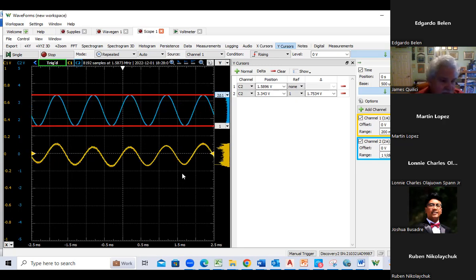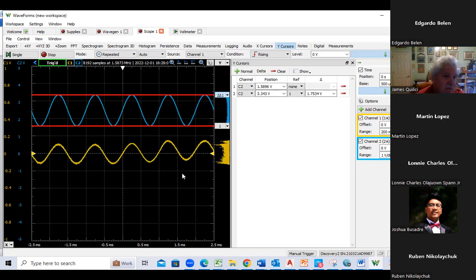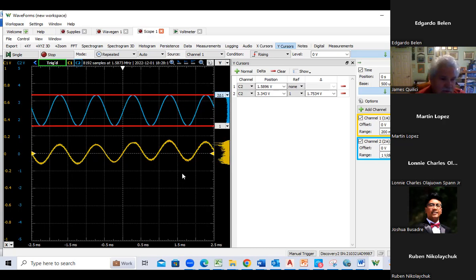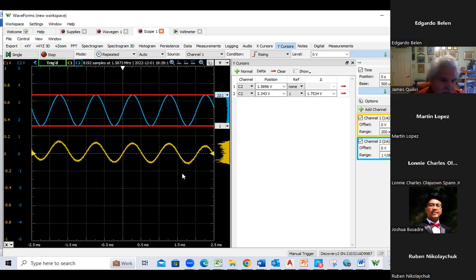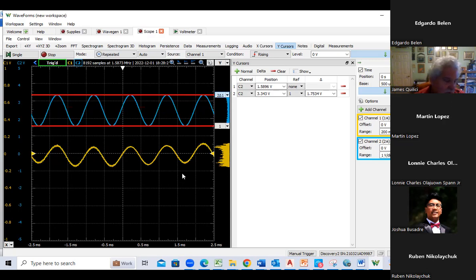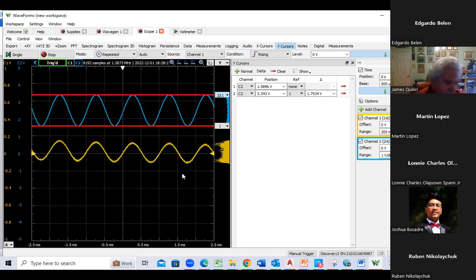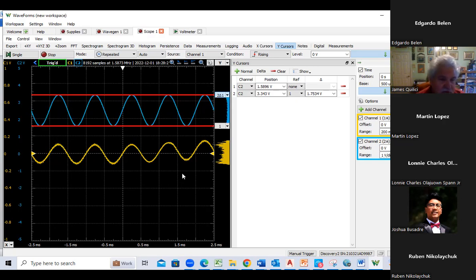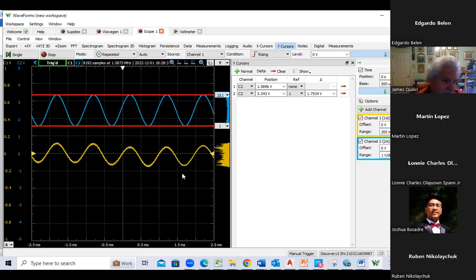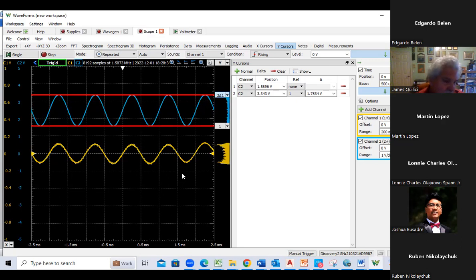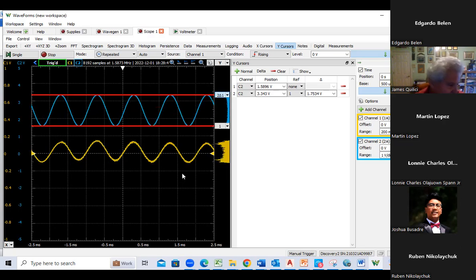And so again, if you're not getting the gain you want, the first thing I would do is calculate the parallel resistance of the load and the collector, divide by the gain, and if your resistor is larger than that, then reduce or modify that resistor accordingly for REA. So first you change the values of REA to try to get your gain where it is. And then if you find the collector is shifting downward or upward, then you might want to consider changing the collector voltage value as well.